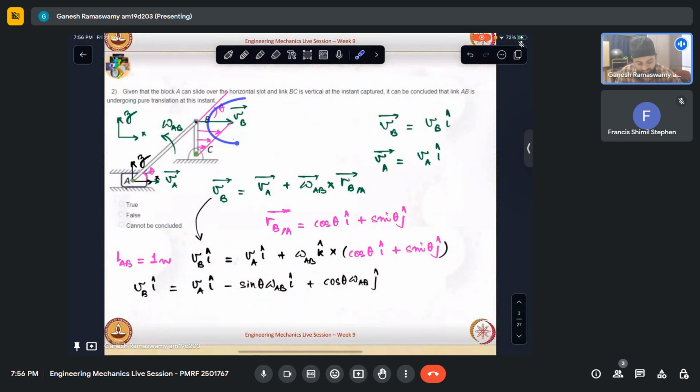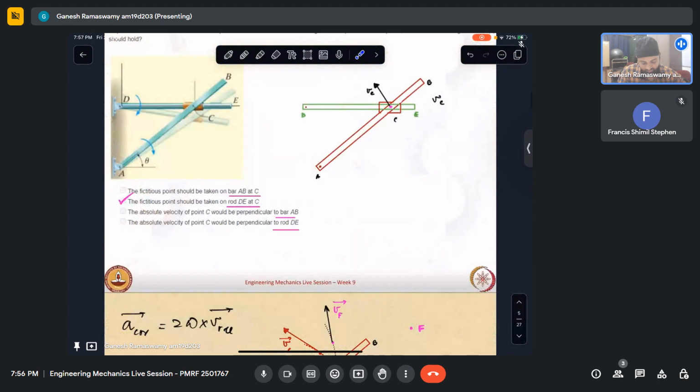If we can actually see that those two are parallel, by virtue of that being a rigid object, we can resolve those two velocities along the line joining those two points, and that would have to be the same in order to keep that body rigid. It cannot be violated, which gives us a constraint to actually solve for other things.